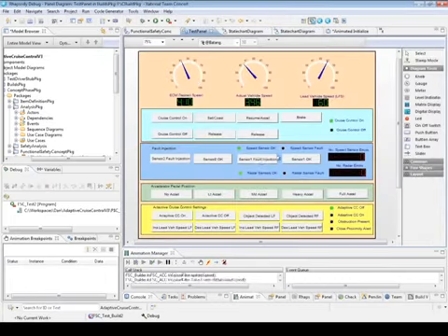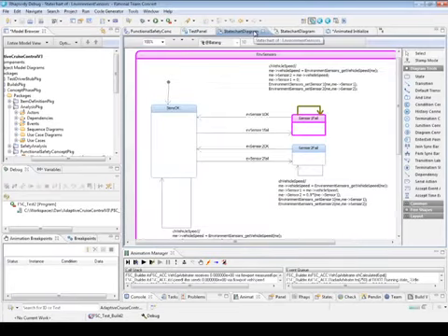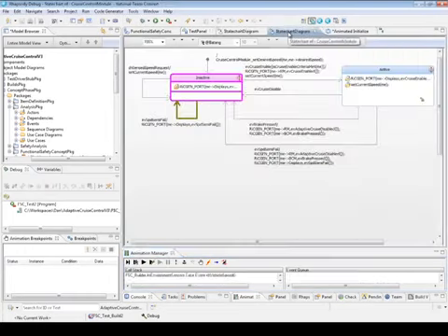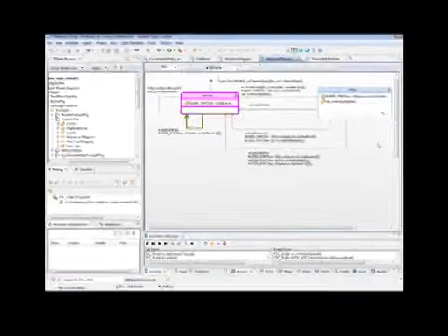Now going to inject some faults into the system, and we can see that sensor 1 has failed, and we'll start to see the number of speed sensor errors increasing, and it will take one more for the system to fail safely and the cruise control to go off. Now gone back to our inactive state. This proves the functional safety concept for safety requirements around speed sensor failure.